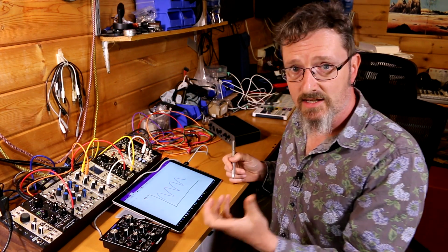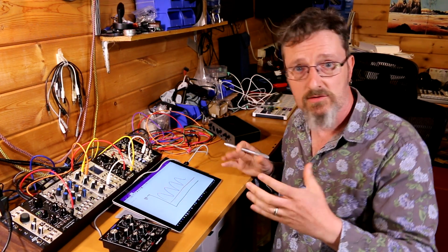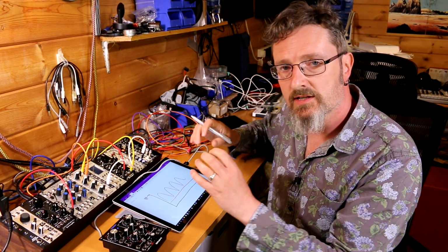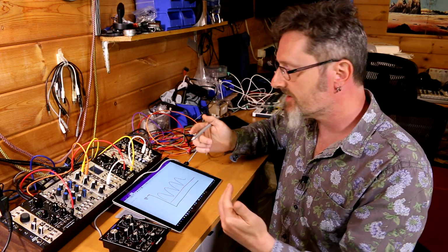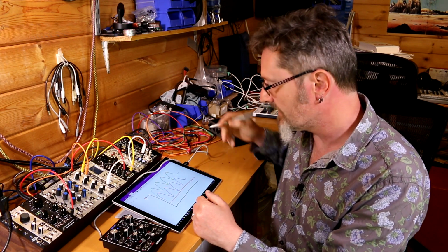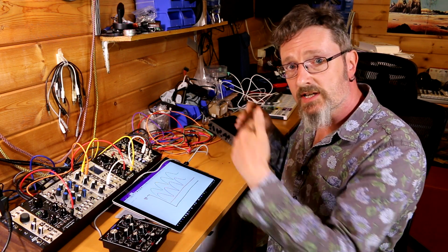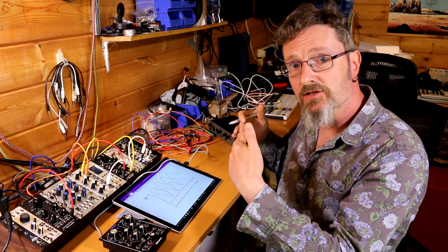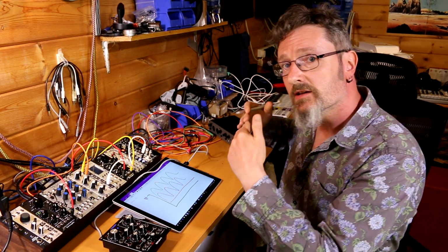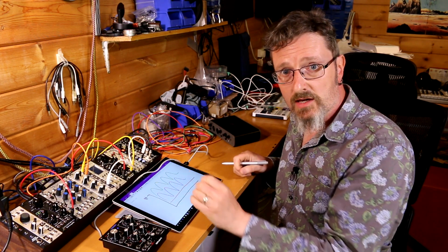If a DC signal is also present, say like that, and that's going to be flat, it's not going to be moving about normally, what happens is that these two signals present in this audio interface get summed, they get added together, and we get a resultant waveform which is like this. Now, it's still the same as the original audio signal, but it's been boosted, it's had this constant voltage added to it, so now it's louder, it's bigger than it was, and there's the danger that that's going to go past the peak point and result in distortion. So that's why we don't want that there.